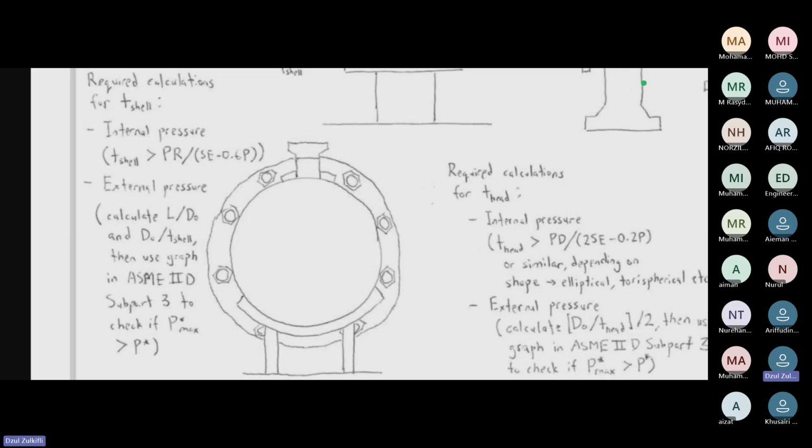So what I know is that API 579 and API 510 have this overlap regarding this procedure of evaluating pitted condition. What I know is that in the latest update, they're going to make it a bit separate. So 510 has its methodology and 579 would have its own more advanced methodology. So the intent is to do API 510 first, then go to 579.